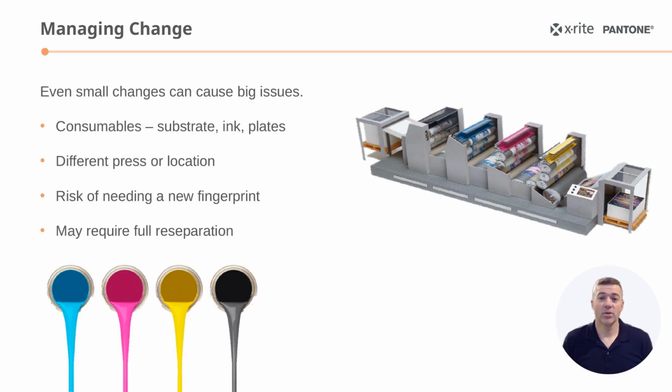If a job moves to a different press, or if you swap out key consumables like inks, substrates, or plates, things can quickly get messy. In the worst-case scenario, you may need to run a brand new fingerprint and even go back to the beginning to re-separate the files. That means more time, more cost, and more room for error.